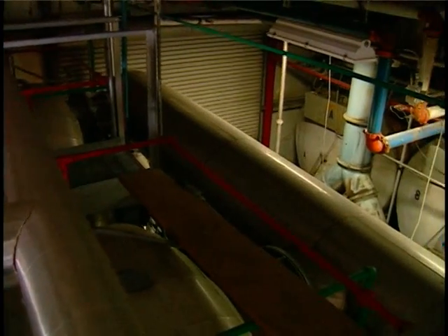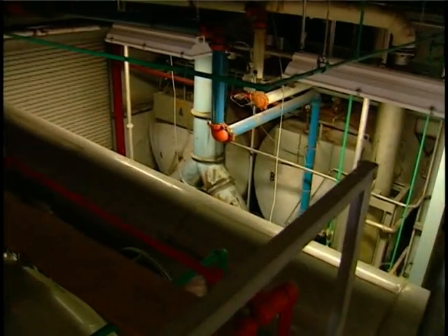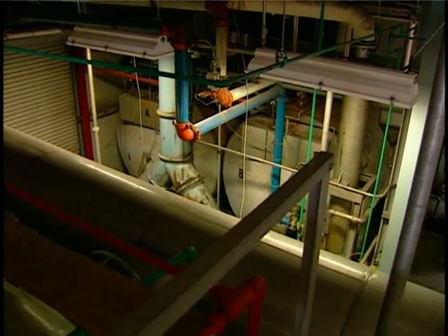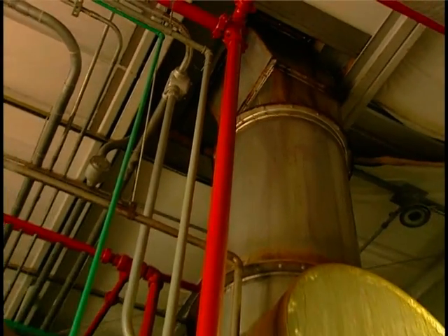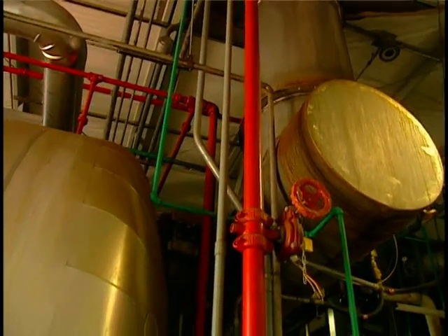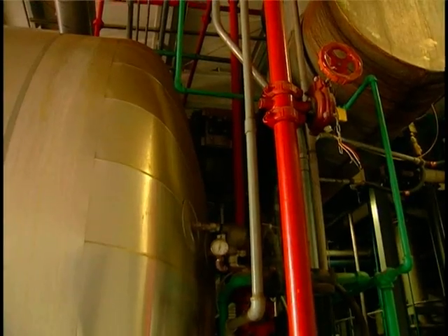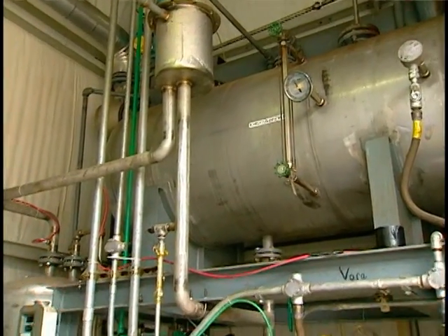The regeneration frequency and cycle time should be compared to the baseline values. Decreased regeneration frequency and time can reduce the capacity of the carbon bed, leading to breakthrough. If information is available, the quantity of recovered organic material should be compared to baseline values.